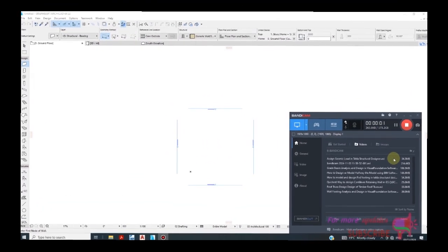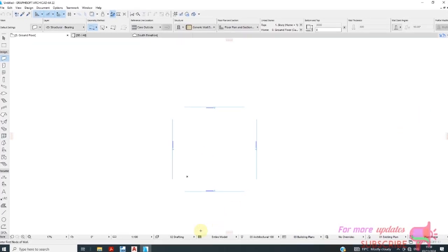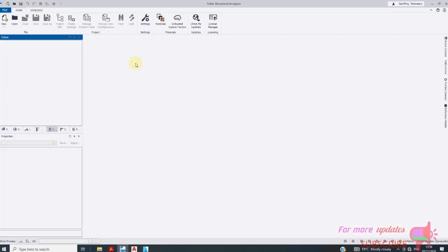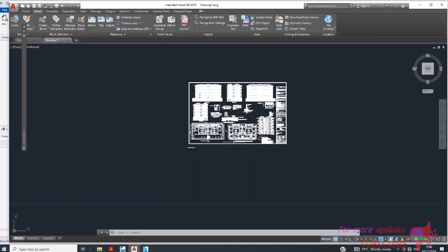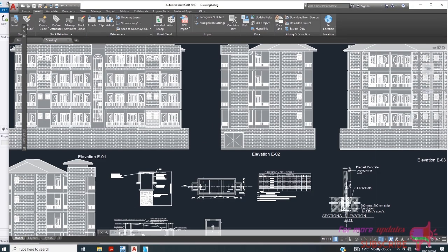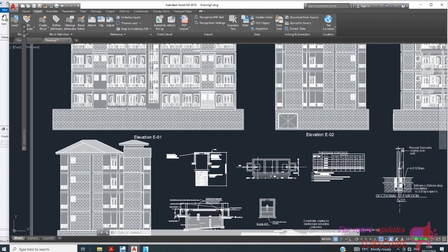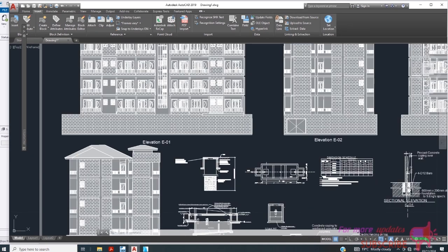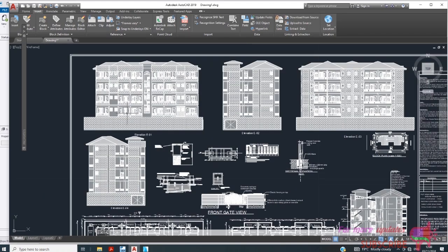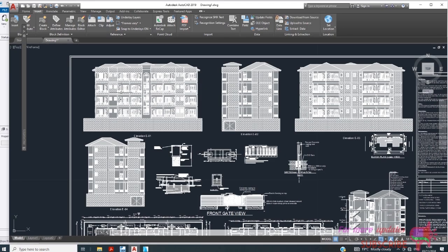Real building design in Tekla Structural Designer 2024. So we're going to model this particular building. It's a reinforced concrete building. It is a G+4 because we normally count the number of slabs that are being carried by the columns. So this is structurally a G plus 1, 2, 3, 4, four slabs. You don't count the roof. So it's G+4.